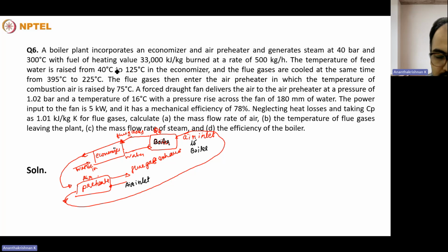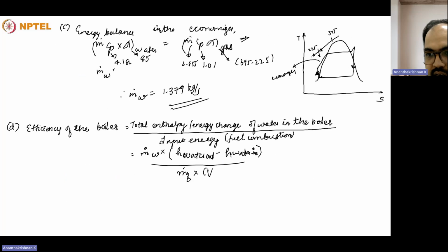Although it is not given in the boiler, in order to make it more efficient, a portion will be taken up by the economizer heat. But we can show that that will be the heat transfer to the enthalpy change of the water. So that will be equal to m dot water times h. So this could be written as points 2, 3, 4: h3 minus h2.